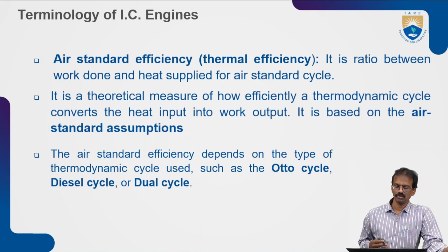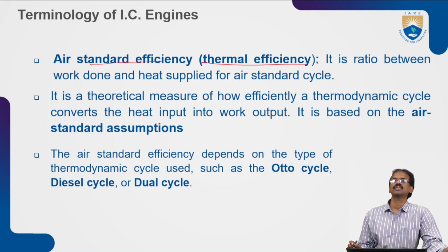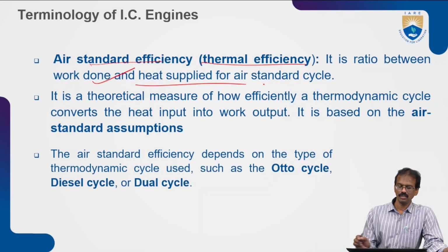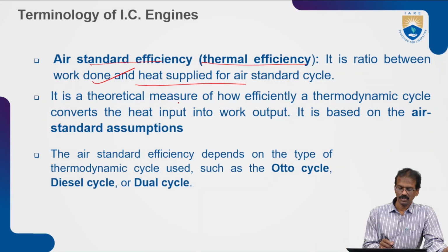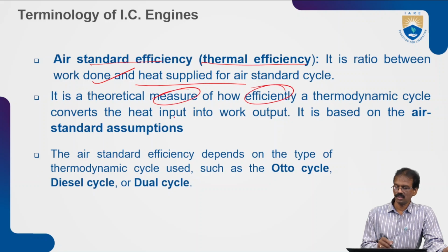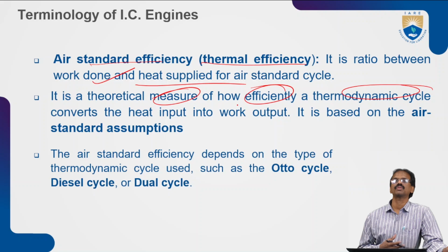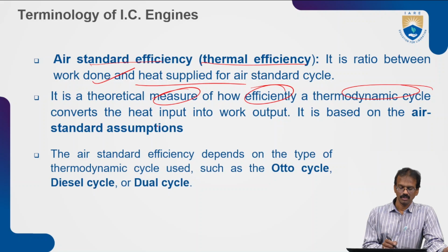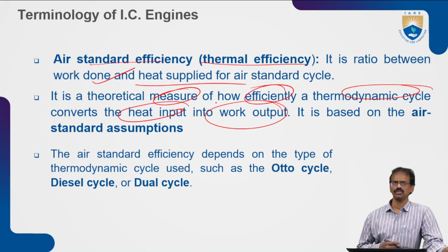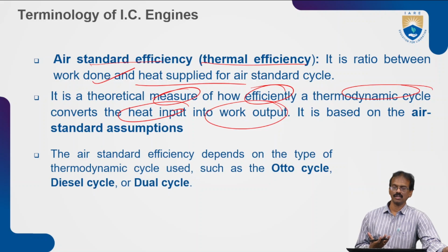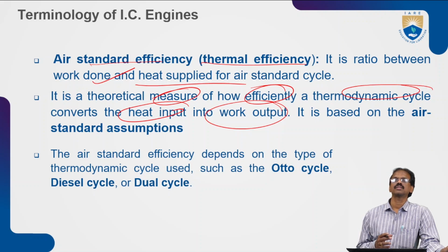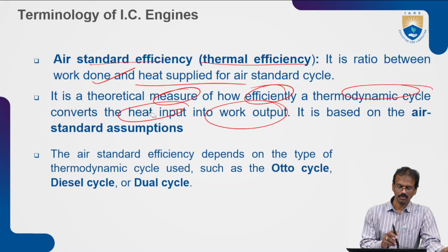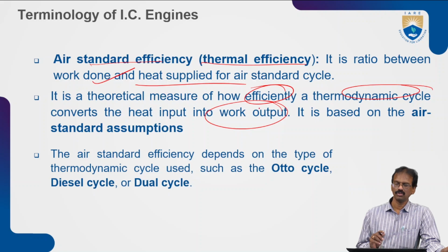Air standard efficiency is also very important. Air standard efficiency is nothing but the thermal efficiency. It is the ratio between the work done and the heat supplied for an air standard cycle. So it is a theoretical measure of how efficiently a thermodynamic cycle converts the heat input into work output. You know that a heat engine is nothing but the conversion of heat energy into mechanical work output.